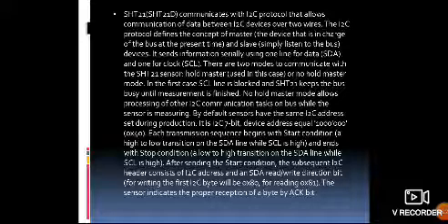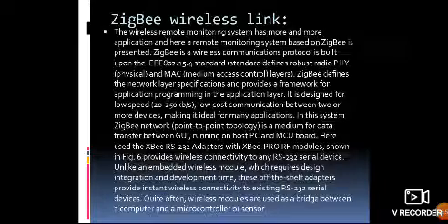The I2C protocol allows communication of data between I2C devices over two wires. In the first case, the SCL line is blocked and the SHT21 keeps the bus busy until measurement is finished. No hold master mode allows processing of other I2C communication tasks on the bus while the sensor is measuring.